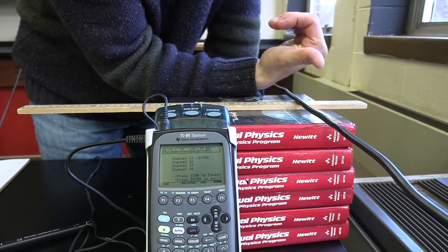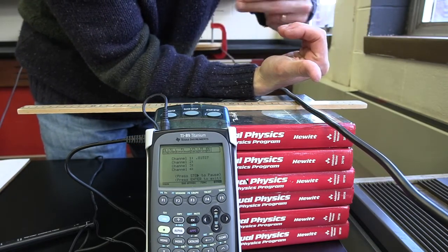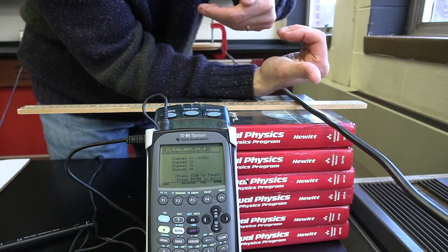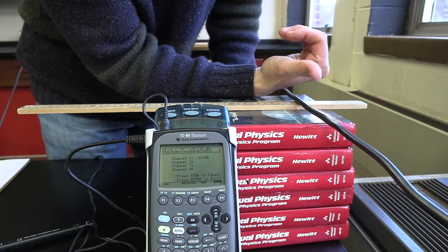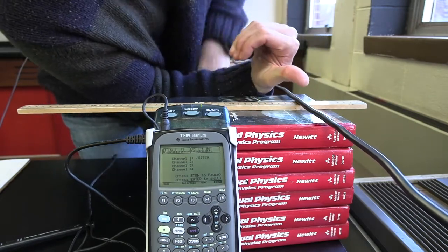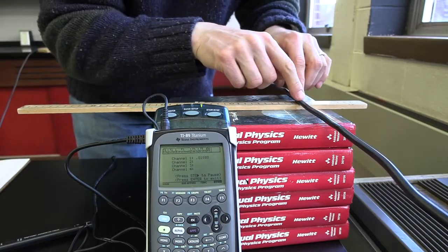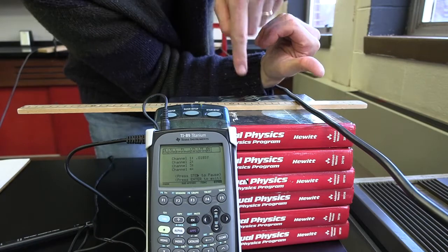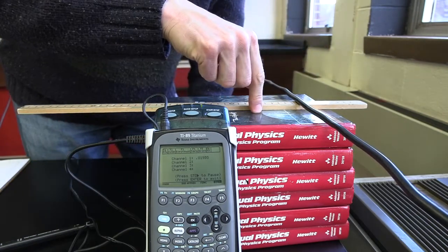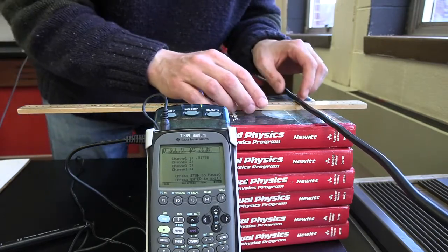At the top here, the magnetic field goes basically toward your left. The Earth's magnetic field goes this way, the wire's goes this way, so we don't want to measure on the top. Over here, the Earth's magnetic field goes down, the wire's magnetic field goes down into these textbooks, and so does the Earth's. So this is where I want to make my measurements.